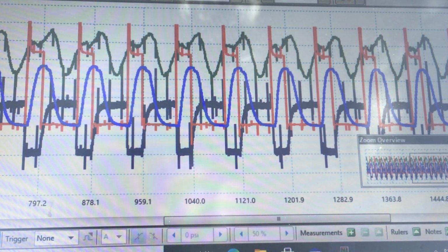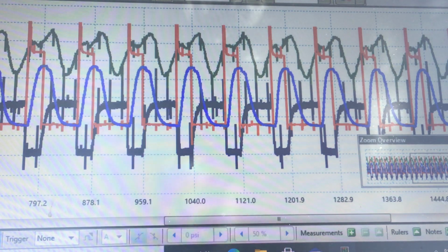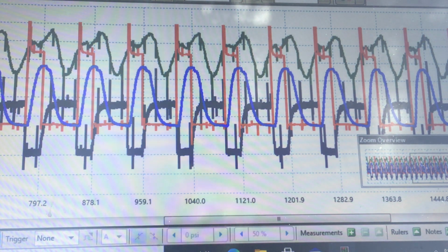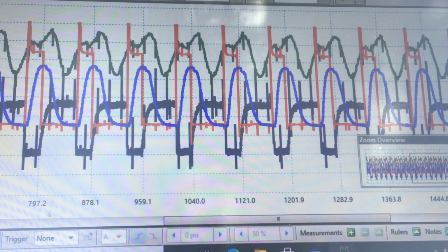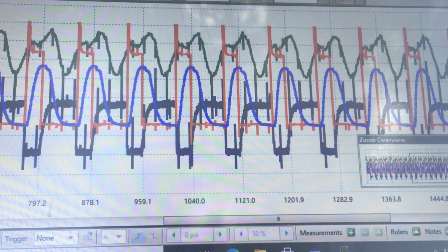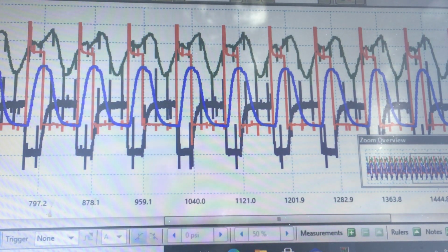If you ever had one, sometimes these vacuum switching solenoids can be very intermittent. I've seen them come with a check engine light, an evap code. You test them 30 times and you cut the car loose and it comes back 2 days later. It runs the monitor and it fails it because they're very intermittent. With this method, we may be able to pick something out. We may see an anomaly in this circuit, so we'd know where exactly to make our diagnostic decision about what component we're going to change.